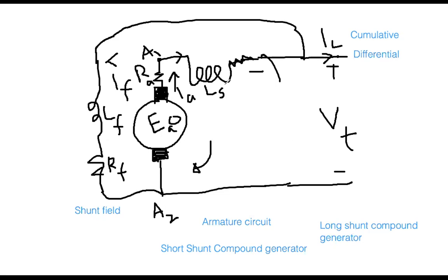So what is the difference? Everybody look. First, this is the IA current, and because this is connected, the same current is going through the series field. After coming here, something is going to the load, and something is going to the field, the IF current. Because this is the series field, after coming here it is divided into two parts.